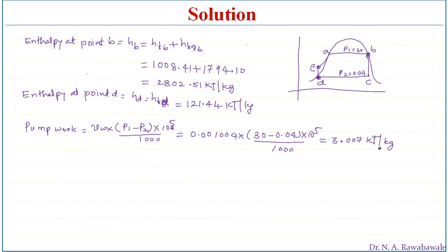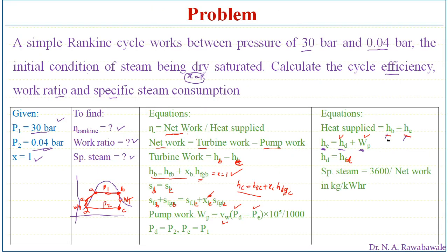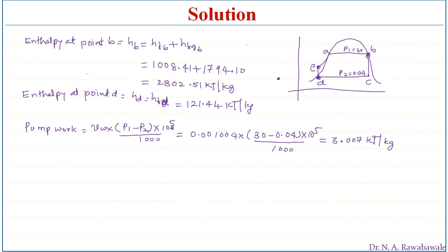So once we know pump work and we know HD, we can find out HE. Once we know HE, we can find out heat supplied. Enthalpy at point E is given by HD plus pump work.